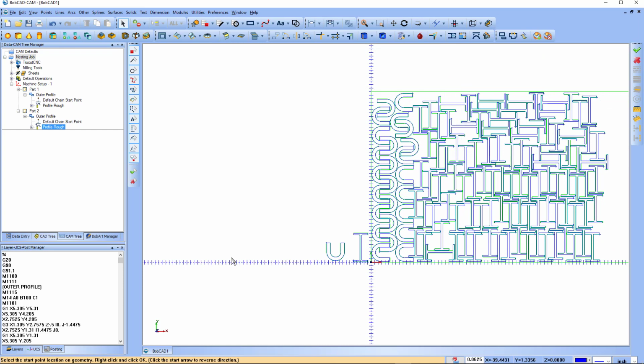In the next video, we'll talk about laying out more custom parts using some of the parameters under advanced posting, and that'll involve controlling the height control, turning the height control on and off for different parts, changing the cut speed for different profiles, and laying out open contours and laying out holes for piercing center marks. So that'll be coming up in the next video.